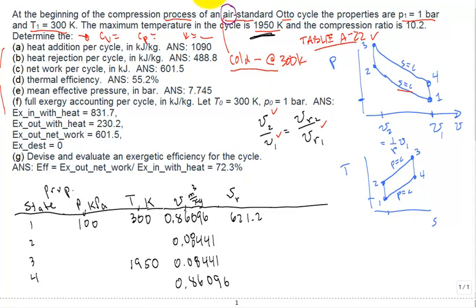And it comes in at 60.902. More digits in there, but now that you know the V sub R at state 2, you can look up the temperature at state 2.